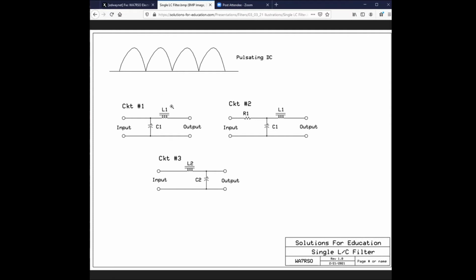Now, what's more dangerous, 110 volts AC or 110 volts DC? 110 volts AC is more dangerous than 110 volts DC because the 110 AC can cause irregular heart rhythm called ventricular fibrillation or heart flutter. Now, if you went up to a higher voltage, let's say 220, 440, higher voltage can cause your muscles to cramp, your chest to cramp, and even stop your heart from beating. There is a better than 50-50 chance that your heart will start again if you can get off of that circuit soon enough. That's a given. I think God has built that into our heart so that it actually will do that, okay? Just a factor.